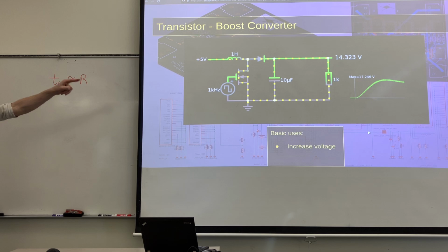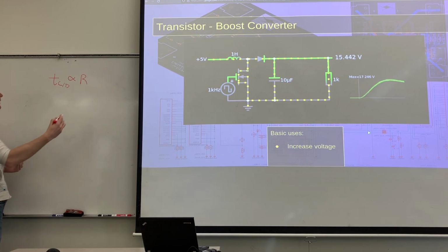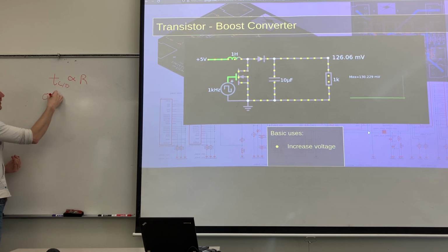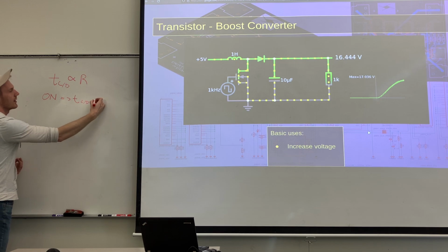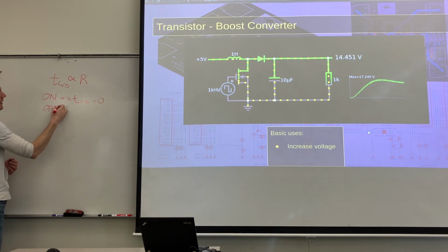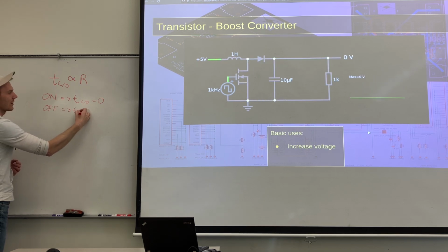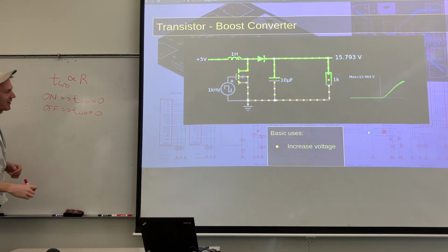But when you put in the loaded circuit, when the MOSFET is not gated, when it is not conducting, now your circuit has actual resistance in it. So let's say on, your time constant is effectively 0. Off, your time constant is not 0, is really all we care about here.